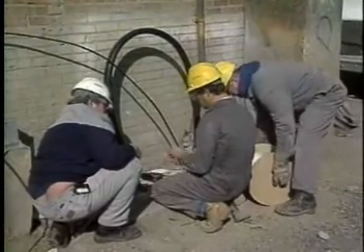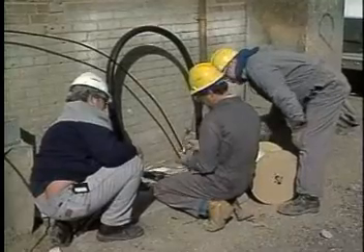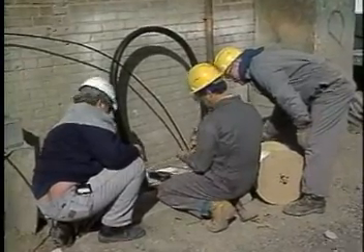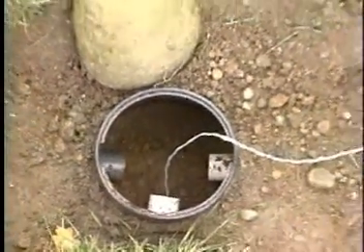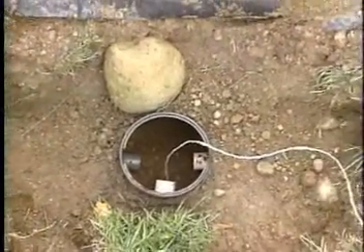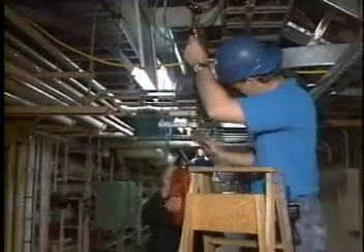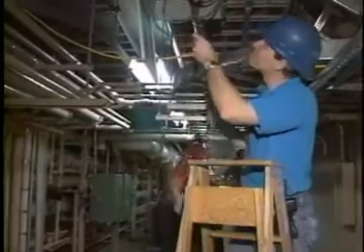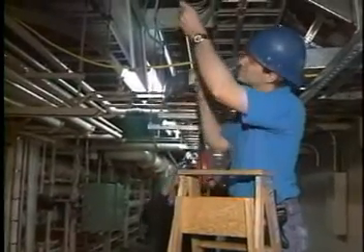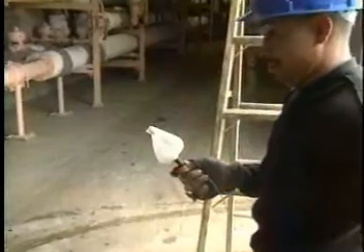To pull in a cable, a pulling line must be in place along the planned route. This line could be a nylon rope, mule tape, or even a pre-existing cable being vacated. It may be snaked through a plenum area or be fished through a duct or conduit. An efficient way to place pulling line in existing duct is by vacuum.